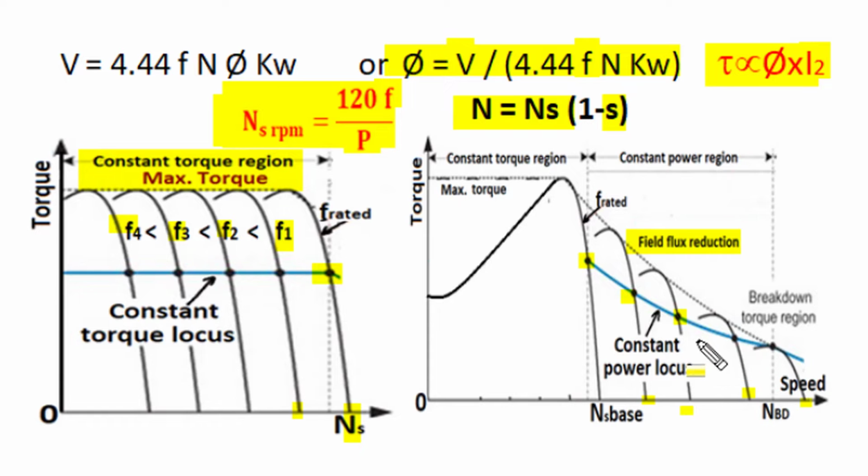And when increased speed shifts the torque-speed characteristic to a higher synchronous speed, our operating point can shift to a new high speed torque characteristic only when it is a constant power type of load, where the load torque requirement for increased speed gets reduced, and we get considerable control of increased speed by increasing frequency at constant voltage, and this control is known as constant power region control.